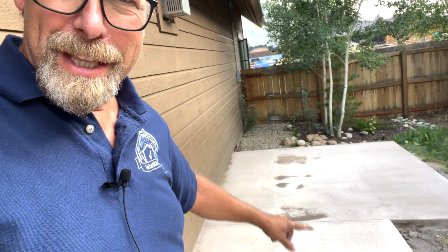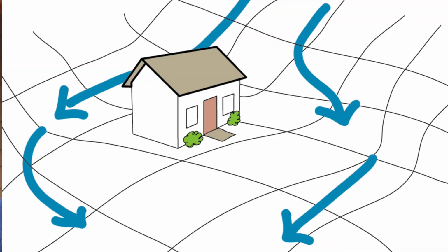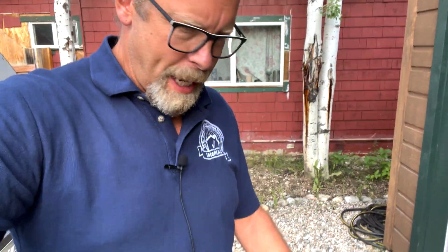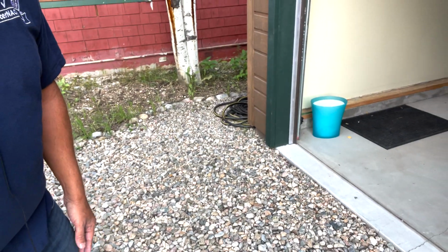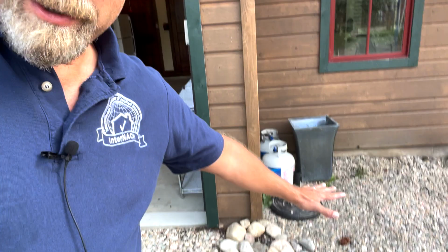And it's causing these cosmetic stains. I wouldn't worry too much about it. And it should drain away from the house. So I'm gonna take a look around the house, make sure the drainage around the house is sloped properly away, down 6 inches in the first 10 feet. So in the front of the house, I see neutral grading, and I'm on a driveway. And in front of the driveway, there's a lot of gravel. In front of the house, there's a lot of gravel.